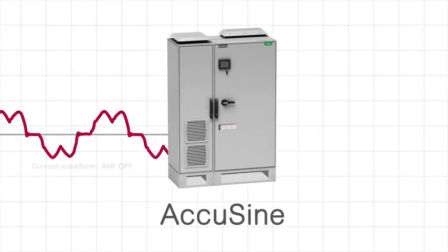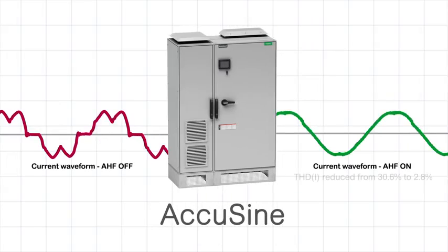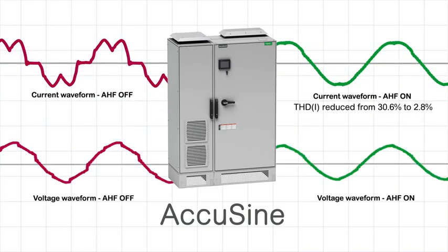AccuSign is ideal to remove the high-frequency current from your distribution network, which in turn reduces the voltage distortion by stopping the flow of high-frequency current through your electrical network impedance. The reduction of total harmonic distortion current and total harmonic distortion voltage removes the stress on your distribution network.